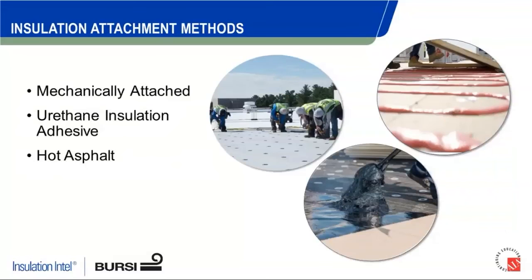We have a lot of different options on how to put the system together, or your insulation together. You can mechanically fasten all of your insulation down. You can mechanically fasten part of it and then adhere part of your insulation above that, or you can adhere the whole thing using either urethane insulation adhesive or hot asphalt. A lot of different options, and all are good options, bringing different characteristics to the table.